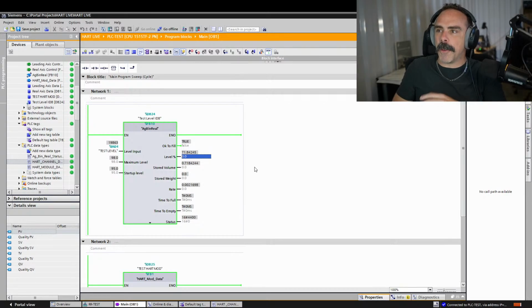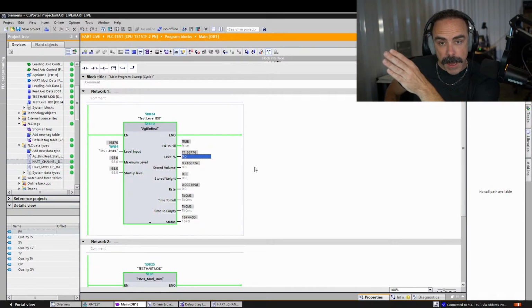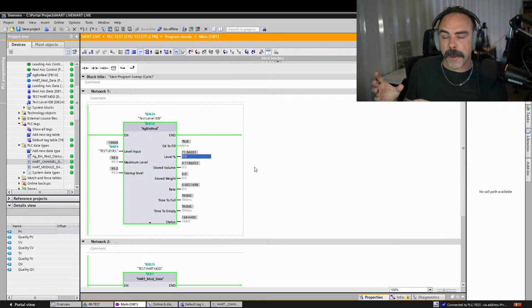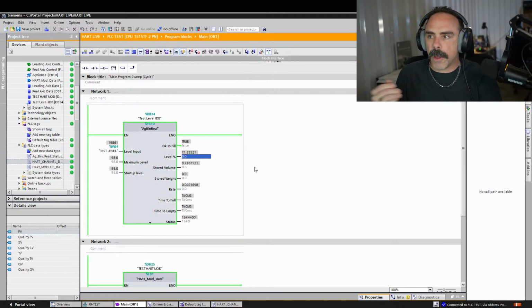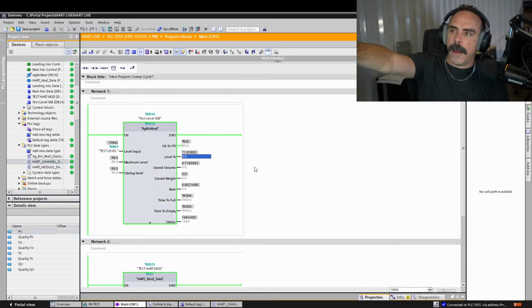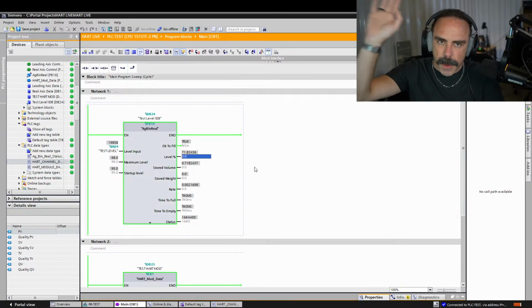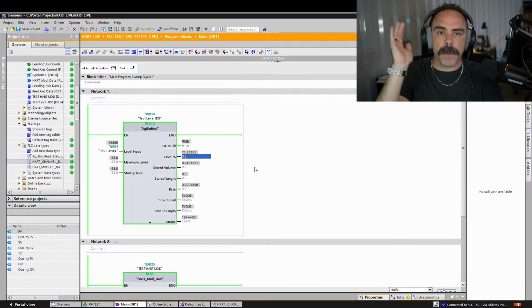But if you use the percent, you put it up there, and that motor's running at 40 amps and it's 10%, you're like, oh, okay, I'm good. It's just magnetized. It's not even pulling any load. Or 30%, all right, whatever. And you could go from there. So all of that is to say, my block outputs percent.